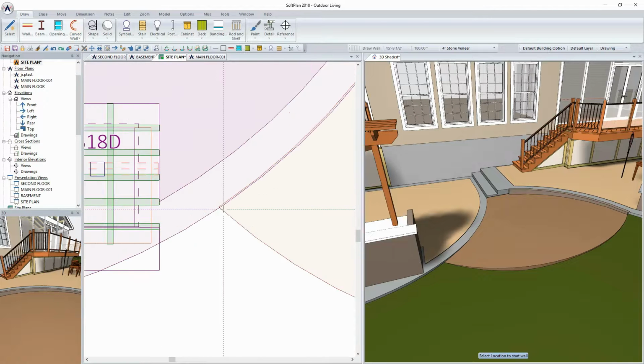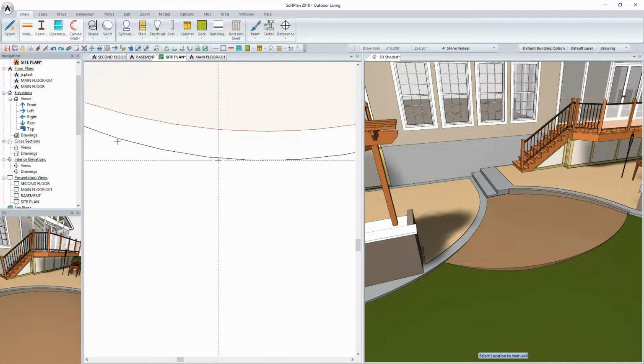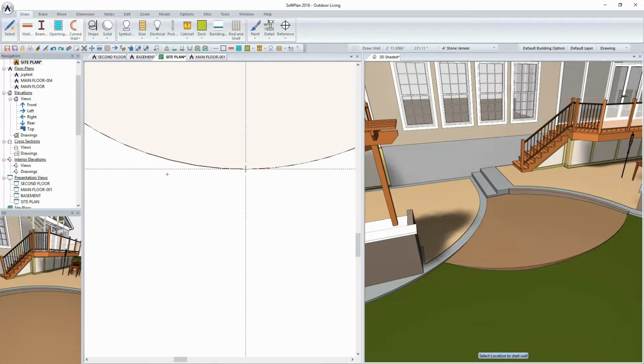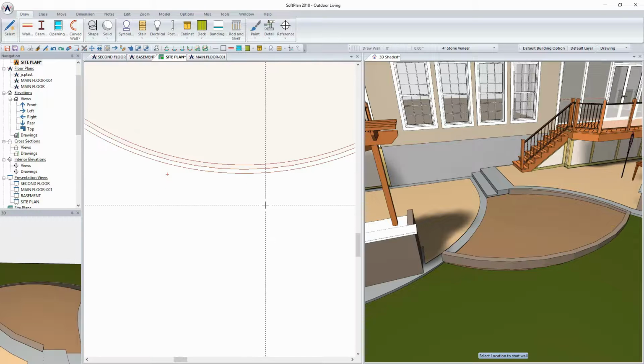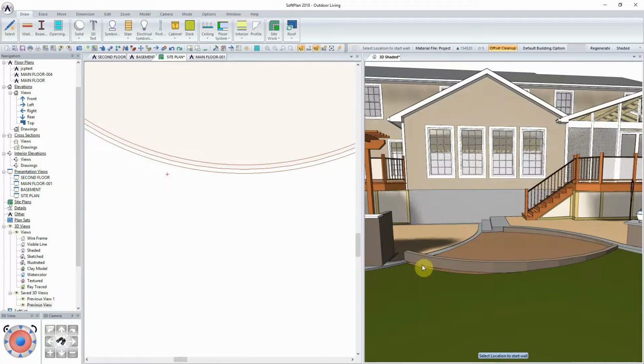I'm going to pan out and then click for the start point, and then holding the mouse wheel down and a combination of zoom will allow me to find where I want to place this wall, and we see that it's going to be placed all the way across. Now in this case here, because of the slope of the property and what's happening, as this wall holds the same offset in height as the previous wall drawn in there for surrounding this, we can see actually that the wall winds up going above the ground.